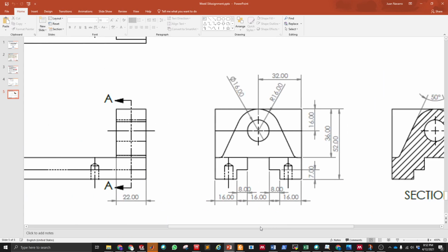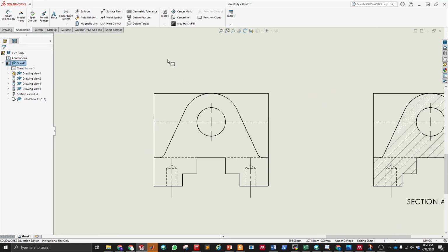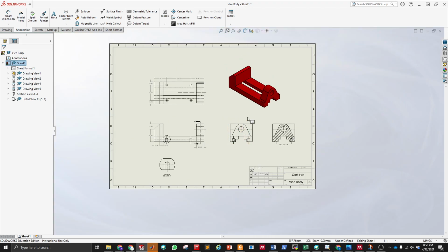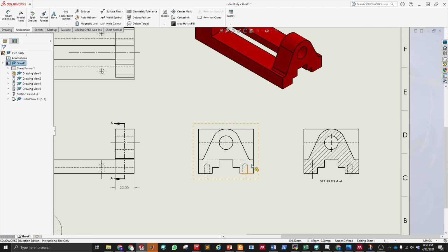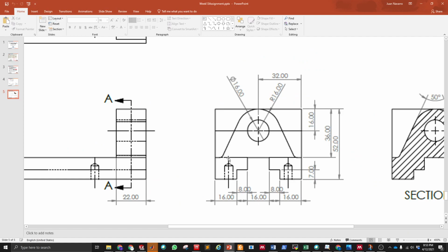Okay, and then for the side view, we have all of this information. Seems a little bit chaotic there. But the point of adding most of the geometric information in this view can help the person modeling this part, knowing that they should start with this view because it has most of the geometric information here.